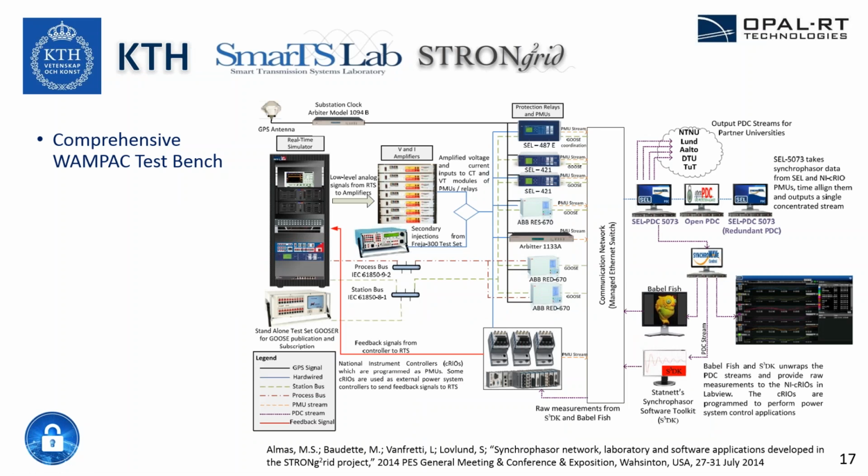So KTH have a very comprehensive wide area monitoring, protection, and control test bench. They have a real-time simulator that's connected to real hardware in the form of PMUs and protection relays. They have amplifiers that create a high-power interface between the two. They have controllers in the loop that they've custom designed using basic National Instruments modules.